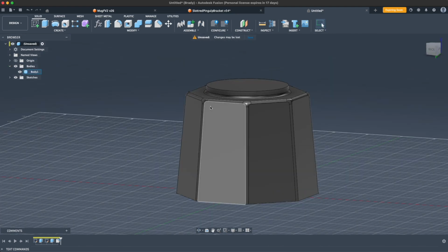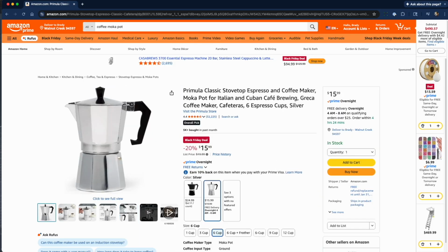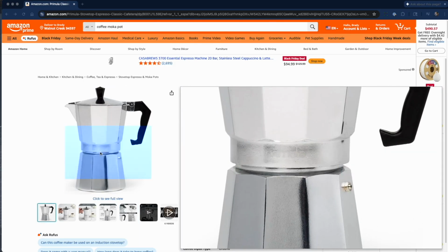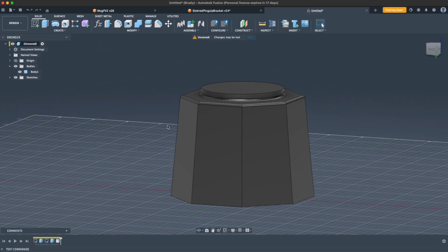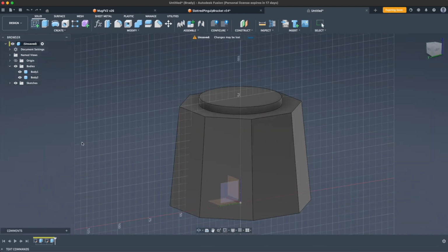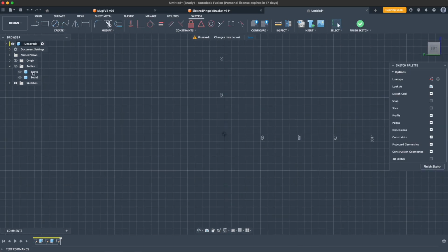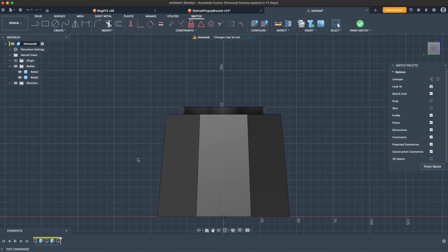So that's all good, but what if we wanted it to look a little bit closer to the example? You'll notice it's got this chamfer that runs across that edge that gives you this really interesting surface. So what I'm actually going to do is undo some of this, and I'm going to show you how to do that. So what we'll do is create a sketch in the side view. So I'm going to turn off bodies, and turn the bodies back on. I did notice these have been separated. It's okay, we can join those back.